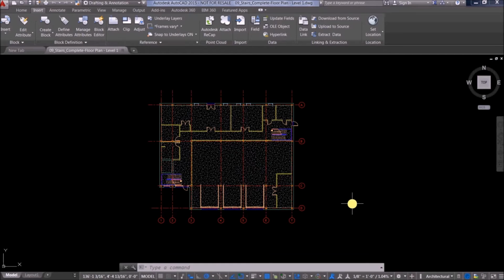And if you don't get it perfect, it's no big deal. You can always move it around in Revit too, but it's a little bit easier to do it right here if you're going to be removing the link and linking it back again maybe later. Because not only are we linking files into Revit, but somebody can also still be working on this AutoCAD file. And if somebody's changing this AutoCAD file, we can see those changes. It's almost like an XREF. So these AutoCAD files are already cleaned up, and now we're going to go into Revit.